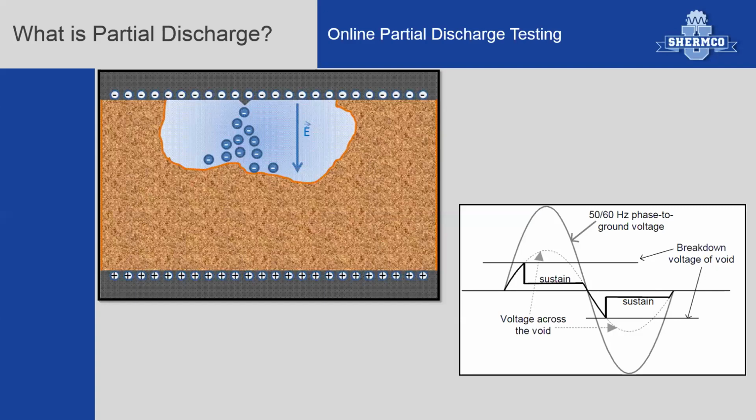Partial discharge occurs in solid, liquid, or gaseous insulating mediums. Partial discharge can also occur in the form of corona, surface tracking, or floating electrode, metal-to-metal discharges, causing degradation of the insulation. Now, once partial discharge begins, it always gets worse.